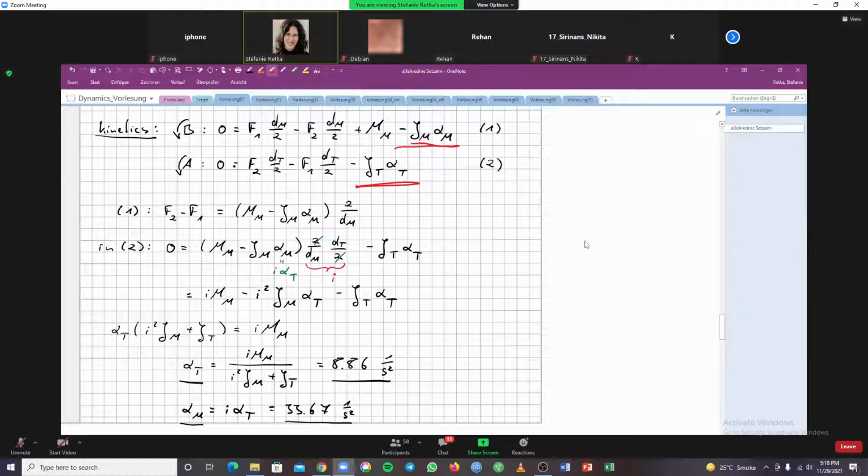It's equal to the inertial moment and the inertial force when we build the sum of all forces. That's the main difference to statics. We have these inertial loads in our system. And considering the inertial loads, the dynamic equilibrium can be set to 0 as well. So that's what we stated in chapter 4 at the beginning, that the sum of all forces, well, I neglect the time dependence maybe, in statics, we would have said this is equal to 0. Yeah, this would have been statics. And in dynamics, this is not 0 anymore.